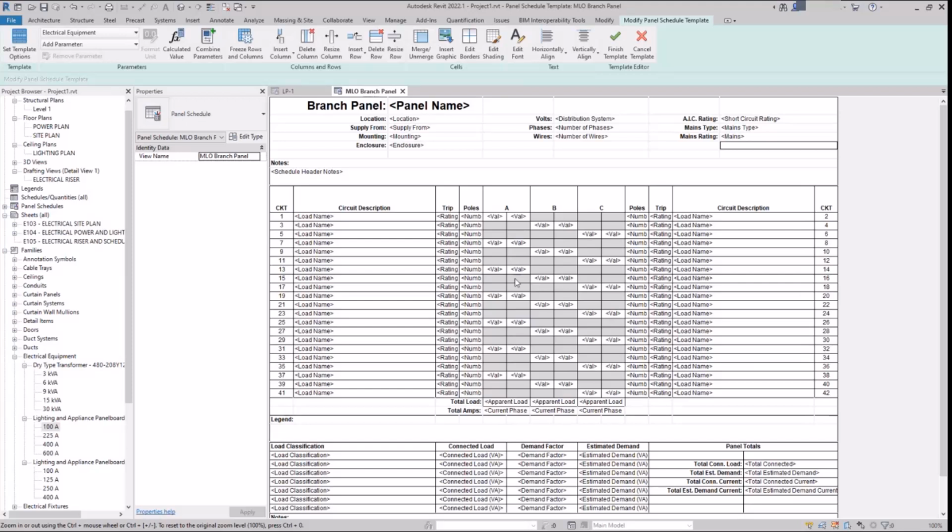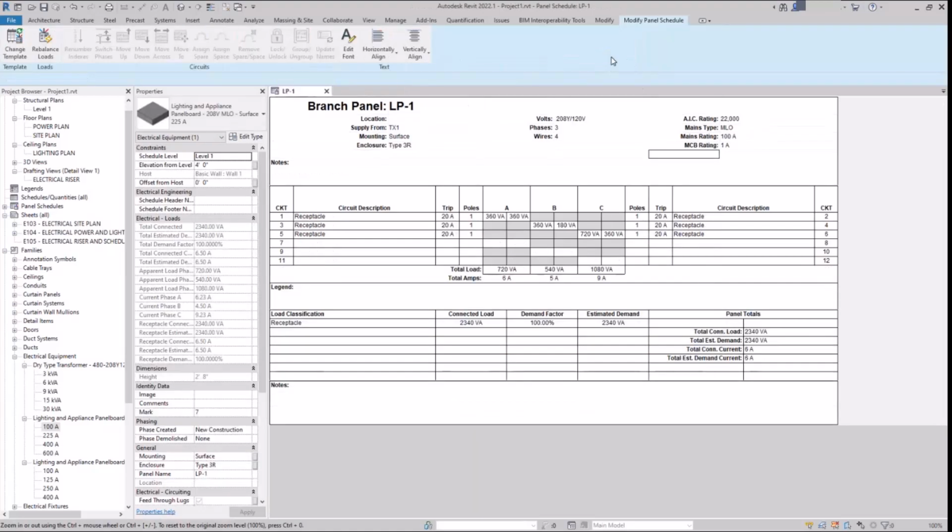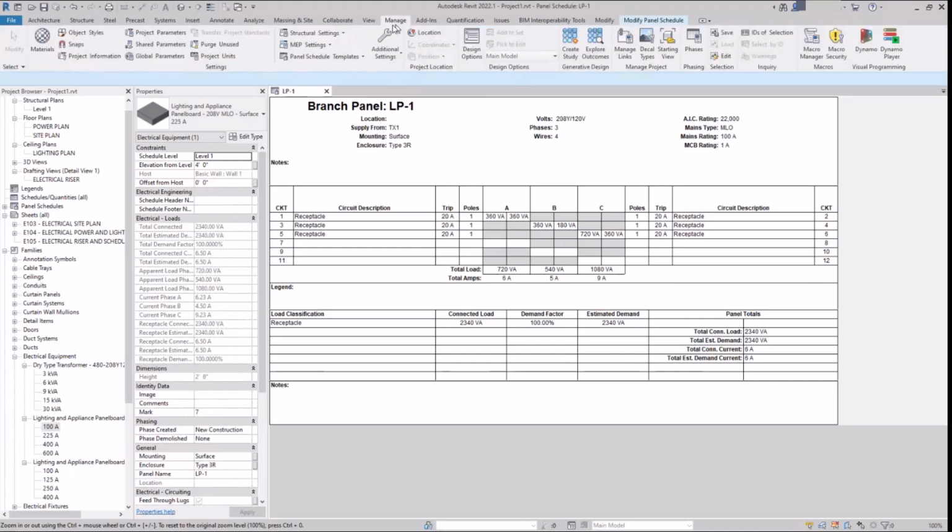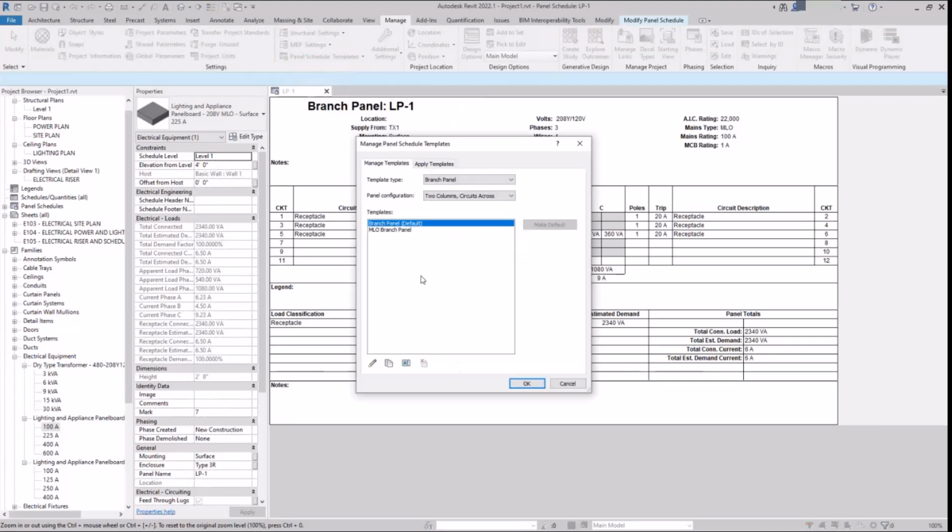on your company. So is the panel schedule template linked to the family, associated with the piece of equipment, like for example, the panel? Is this linked to the panel family? So whenever you load in a panel like an LP1 panel? Yeah, the schedule loads in too, because we already have a panel template associated with that family. It's not something extra that you have to add in, it automatically comes in when you add in a panel from our panel families.